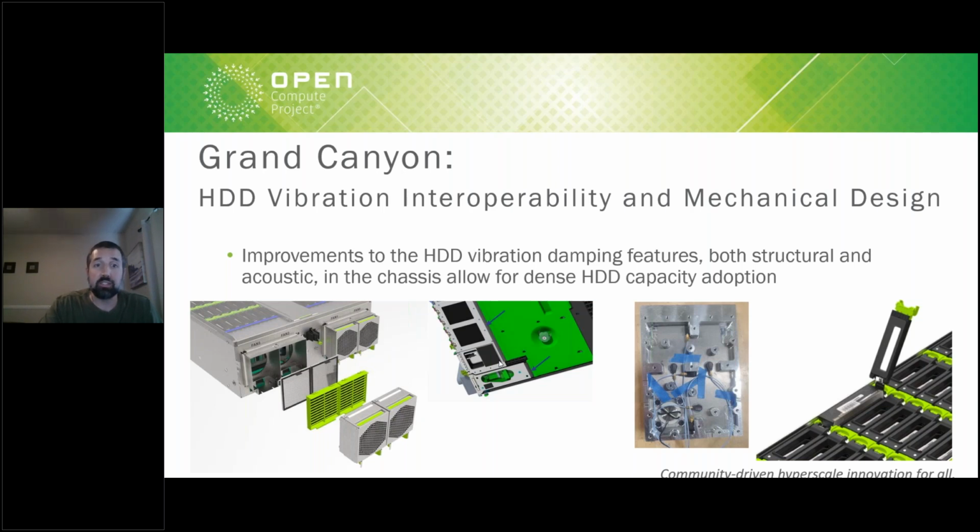Some improvements to the fans themselves were made, including a lower fan blade count and tuning the geometry of the fan blades to help vibration. And the system design accommodates drop-in replacement of a new hard drive latch. You can see that here in the bottom right-hand corner, and one option is to make that out of a stiffer material, which can help reduce the transmission of vibration to the hard drive.